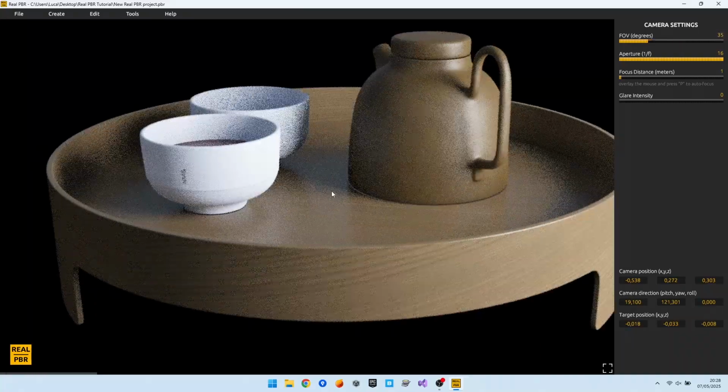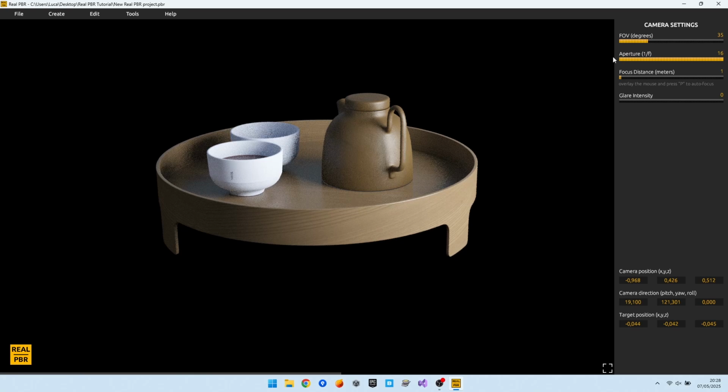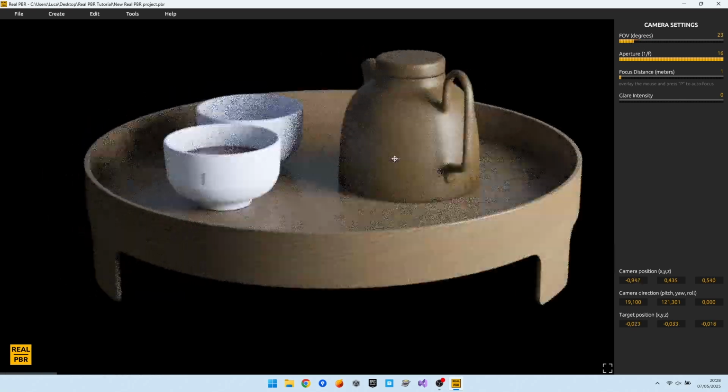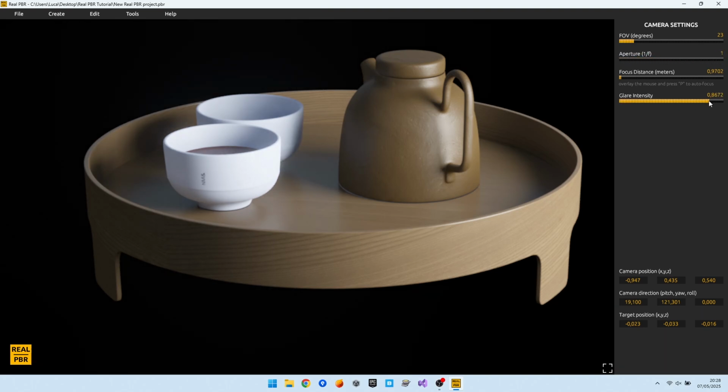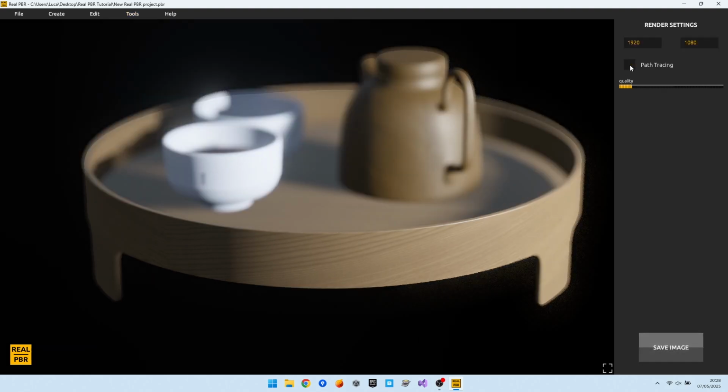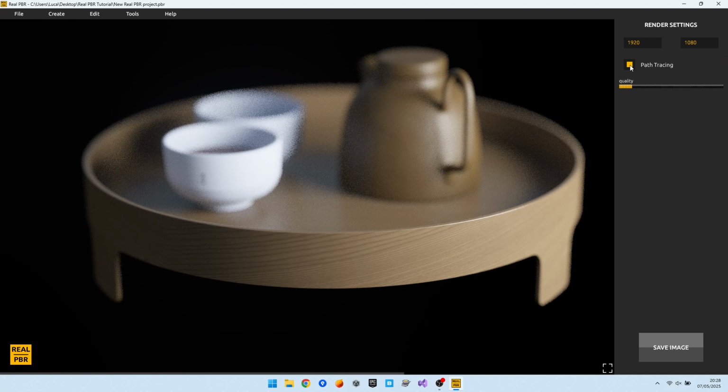The final touch is about the camera position. Of course, this could have been the initial touch. It really depends on your workflow. So in here, I open the camera setting from the tool, and I'm defining the position. Now for the focus, you see that I'm changing the focus by pressing the P button on the keyboard. So P, I meant it as a focus point. So once I click on P, I can define the focus according to the distance from the camera.